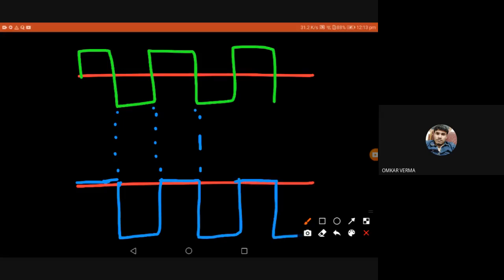Okay. So what is happening? Initially my DC potential was 0 volt. This was my DC level, and plus 5 or minus 5, whatever voltage plus V and minus V, plus or minus 5 was there. Right now I have given a DC shift of plus minus 5 to my input signal. So what happens? Now my 0 and minus 10 is my maximum DC level. Getting it? So this is clamping in a negative voltage. I'm adding a DC level to the circuit.